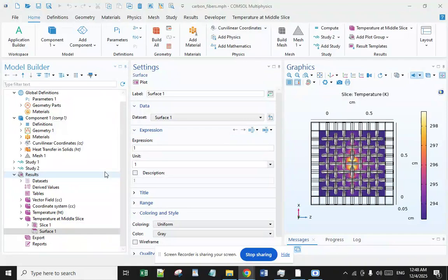And the measurement of the specific heat capacity. The specific heat capacity of all the fabrics and the silicone rubber diaphragm was determined via differential scanning calorimetry (DSC) experiments using a TA Instruments DSC Q100. A DSC scan was carried out in the temperature range of 15 to 140 degrees centigrade at a rate of 5 degrees centigrade per minute.